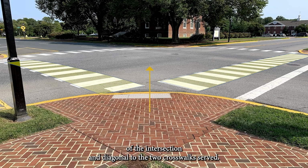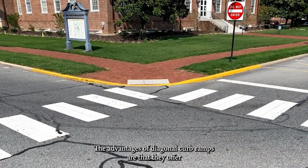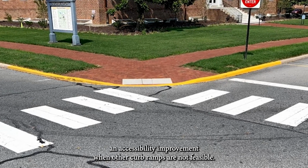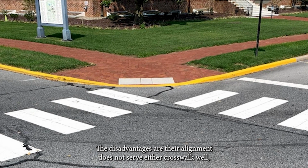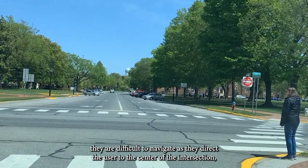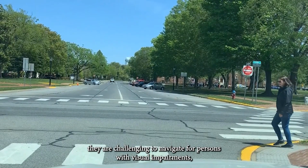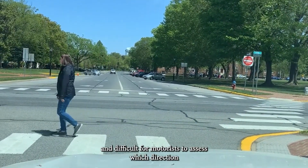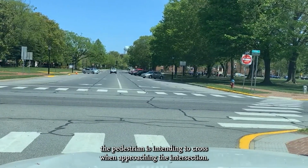The advantages of diagonal curb ramps are that they offer an accessibility improvement when other curb ramps are not feasible. The disadvantages are their alignment does not serve either crosswalk well. They are difficult to navigate as they direct the user to the center of the intersection. They are challenging to navigate for persons with visual impairments and difficult for motorists to assess which direction the pedestrian is intending to cross when approaching the intersection.